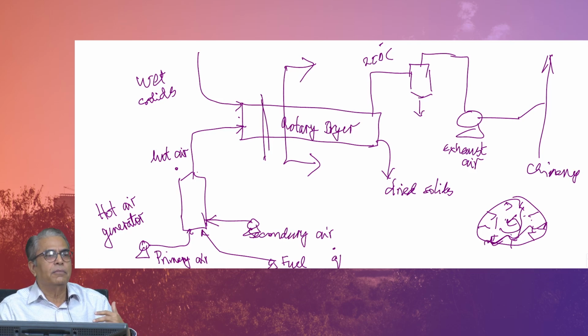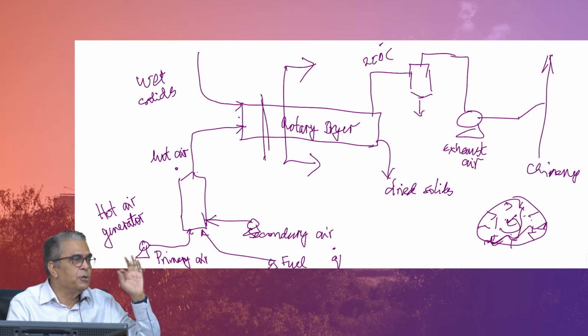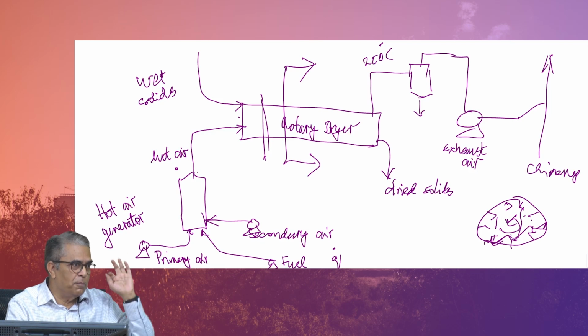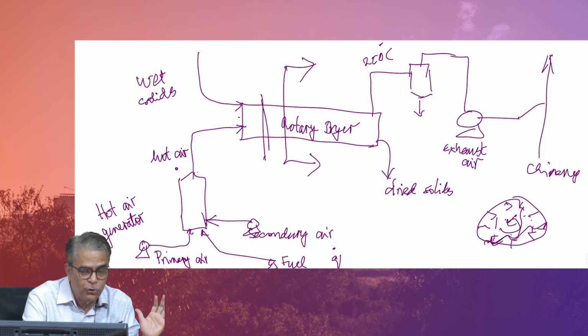Over a period of time, dryer manufacturers have got this done, and they would have found out the logic and told you, you must maintain so much of velocity and this temperature difference dries. Anyway, it is a running dryer in this example. So, the background, if you go through that, you will know. Point is, I am coming to secondary air. After a fuel, which is based on mass balance to dry the moisture, and therefore what is the air that is required to burn, you will find that you have to add extra air simply because you want mass flow rate in the dryer.